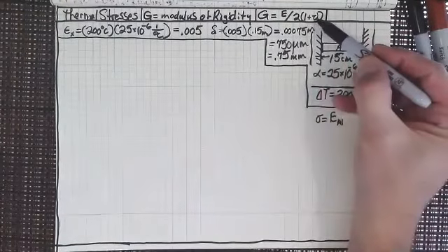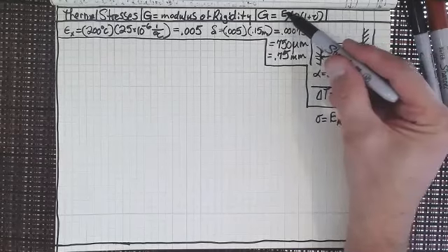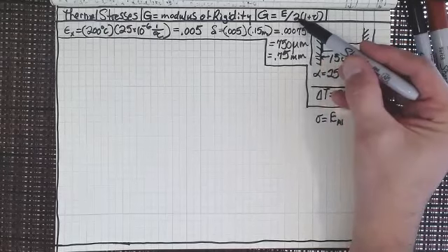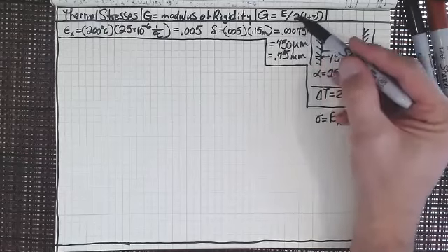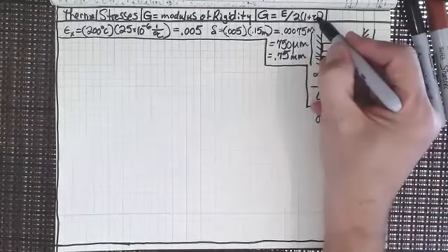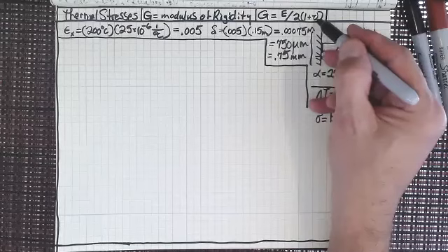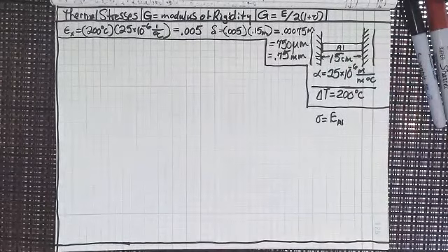And you can see that even if Poisson's ratio was 0, which it would never be, it's going to be greater than 1, that still, that's E divided by 2, right? So it's always going to be less than 1/2. G is always less than 1/2 of E. So if you know what E is, you can pretty much, using Poisson's ratio about 0.3 for the metals, especially face-centered or body-centered cubic metals, get a good approximation of what it's going to be.